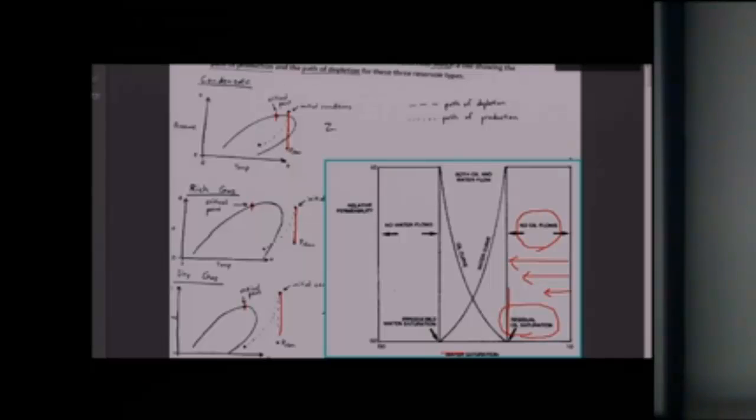So it doesn't matter if you're going to work for an exploration and production company, upstream, or a midstream company. You're always looking at reserves. That's why we'll be looking at that again when we look at our P/Z. We're always interested in reserves because let's say I'm a midstream company and I'm going to process liquids. I'm going to be taking some kind of well stream of a rich gas from a well and I'm going to process liquids. Well, initially, maybe it's making 100 barrels per million cubic feet of gas, and I do a P/Z and I say it's got 24 BCF, but